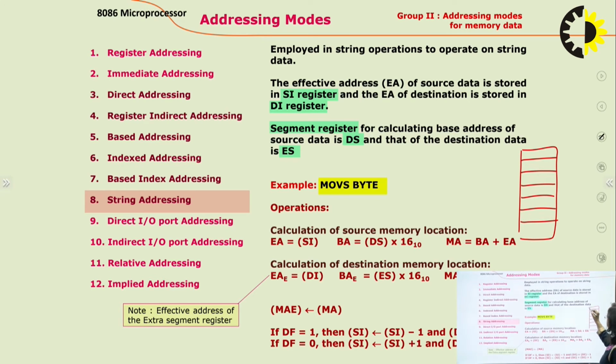If we talk about a string, it means a group of data starting from a particular location. Let the starting address be 20,000 and we are taking 10 bytes of data from this string. Then starting from 20,000, the next 10 locations will be fetched. If each data is 16-bit, then starting from 20,000, since each data will take 2 locations, 20 bytes will be fetched.